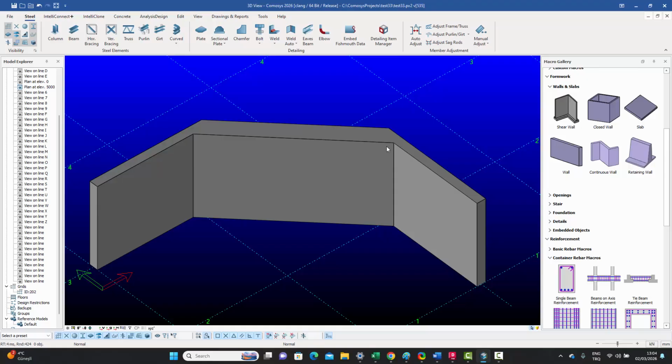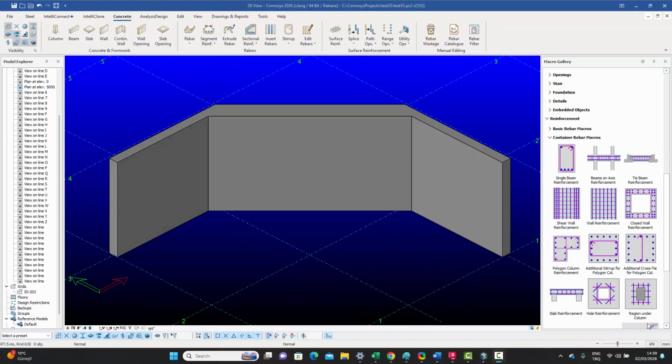And so you can do any way. You could either have a strategy of different walls, in which case you would need to do the end cutting yourself, or you could get a single object either through the folded plate command or through the continuous wall command as well. All these are possible options.